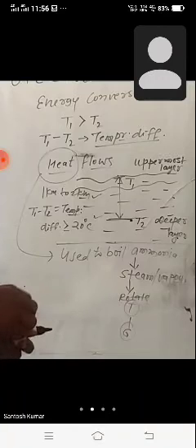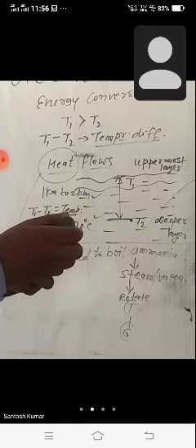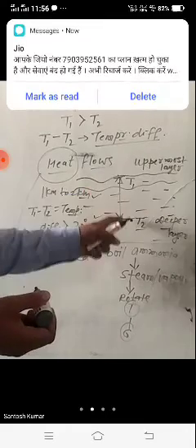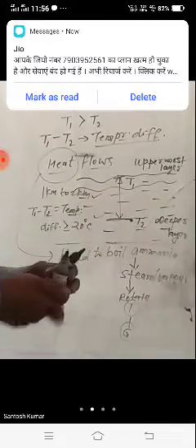And the place where it is harnessed is known as ocean thermal energy conversion plants, or conversion power plants. This is each and every piece of information regarding this. These are the limitations. This should be the condition for the production of OTEC. The temperature difference must be about or greater than 20 degrees C within the range between the uppermost and deepest surface, about a distance of 1000 meters or 1 kilometer, or in your book only it is 1 kilometer.